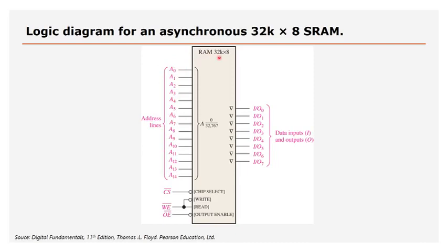And that's why if you've got, let's say, something like a 16K, you will have 14 lines going from A0 up to A13, the biggest one here, and so forth. If you've got an 8K, you will have 13 lines, and if you've got 13 lines, it will go from A0 up to A12. So that's the relationship between the address lines, the number of address lines, and your memory size, the amount of positions inside this RAM memory.